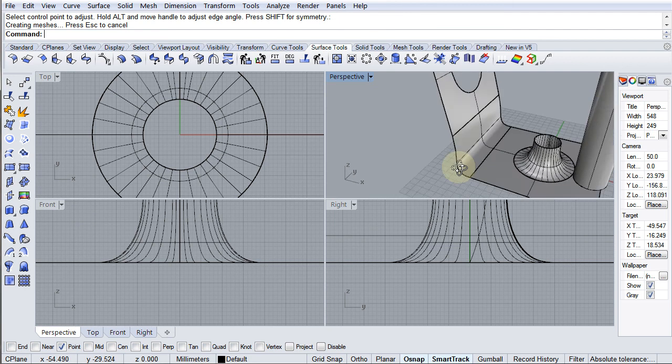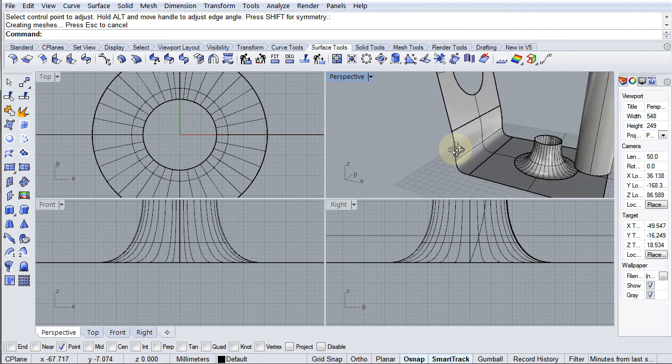Okay, so that's a little bit on blending. Experiment with it, try it out. Try creating some fillets on an object that I've shown you the fillet tool before. Fillets are not curvature continuous, they're tangently continuous. So you can try deleting exploding the object, deleting the fillets and putting blends in their place. You'll find you'll end up with some holes that you might need to patch somehow, but it's worth giving it a shot.